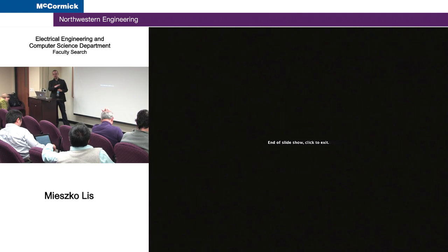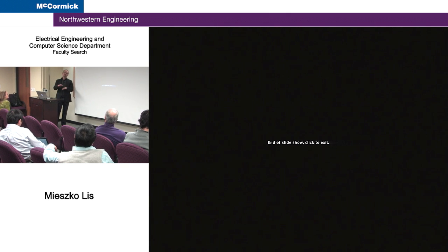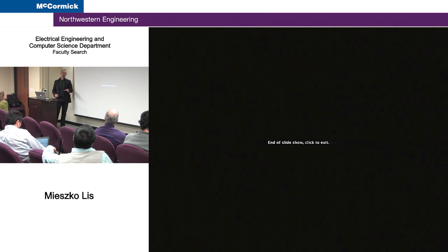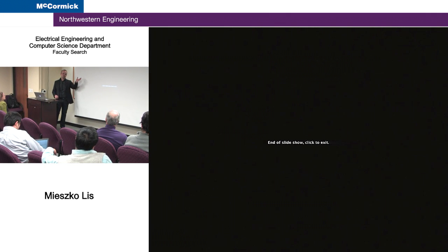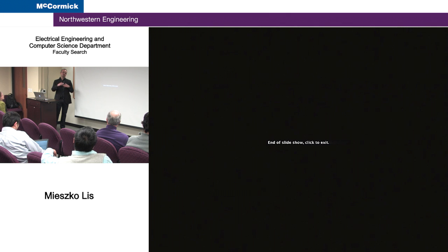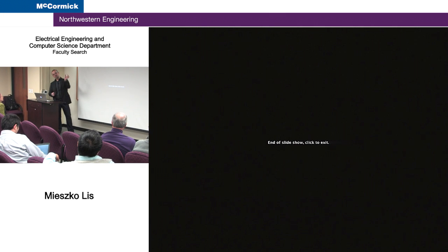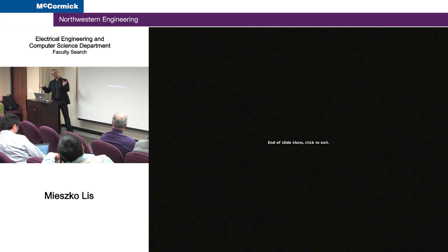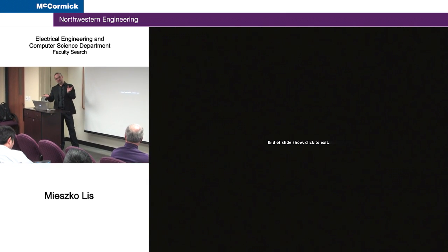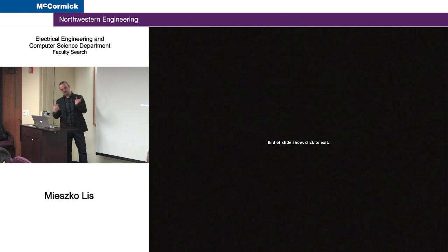The work I described, the chip I mentioned, doesn't have virtual memory. It does not have virtual addressing. In a real system you would actually have virtual memory, and this provides an opportunity to add indirection. Because you have the virtual address that you're using to address, but the physical address is stored elsewhere, you can move things.